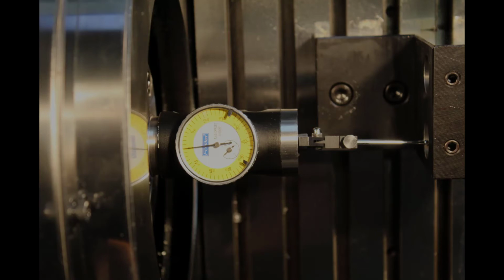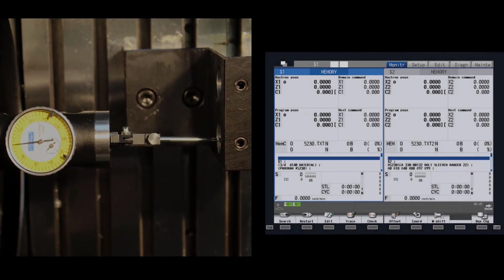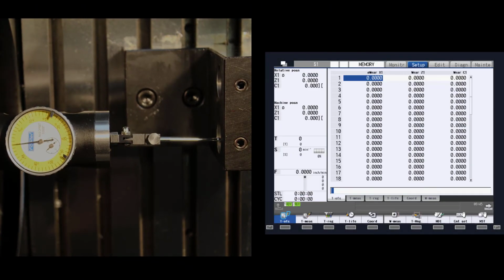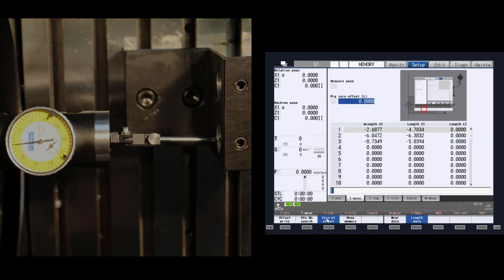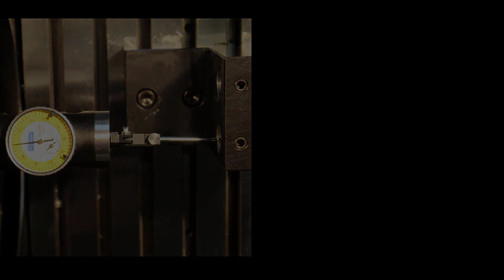To find the center of an ID bushing holder, use an indicator to sweep in the center of the holder. Use the same method that we used to pick up the X-axis offset on tool 1, only place a 0 in the program part 0 area instead of 0.973.